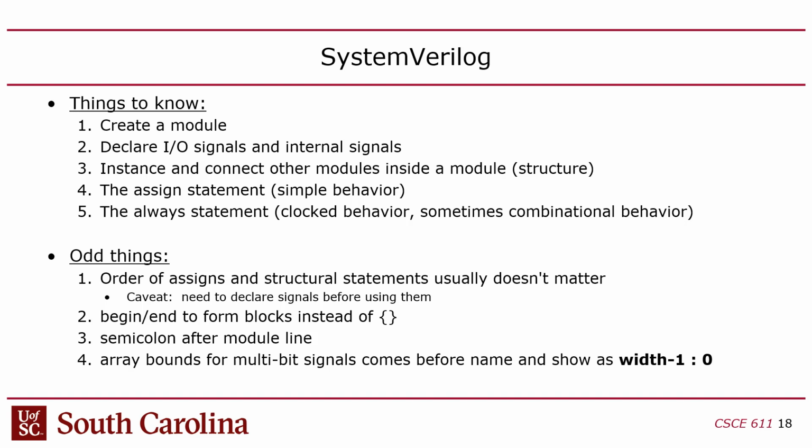The first thing is that the order of the assigns and structural statements, in other words, the instanced modules, doesn't matter. You can scramble them in any order. It doesn't matter because you're building hardware, and SystemVerilog uses concurrent semantics, meaning that the order of statements doesn't matter.